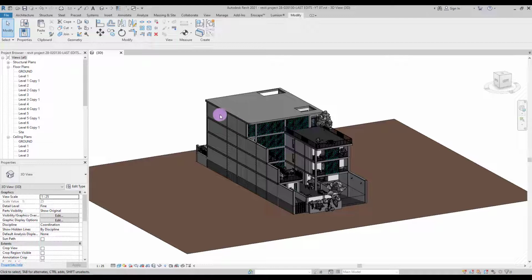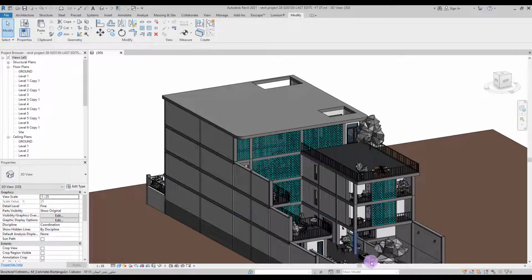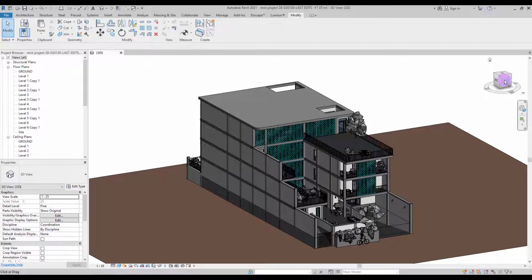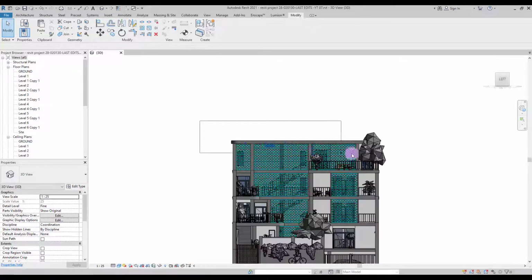For example, make sure your walls or your columns are locked between 2 levels. If you have a wall which is continued from level 1 to level 3 or 4, you might need to cut your wall. So let's start with our roof. Go to one of your views here and select your roof. You can select your lightings in that roof as well.